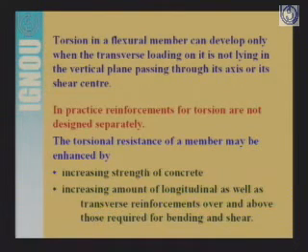And the second remedy is by increasing the amount of longitudinal as well as transverse reinforcement over and above that required for bending and shear.